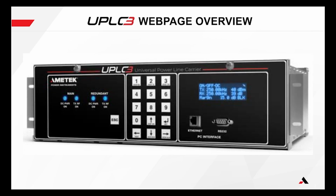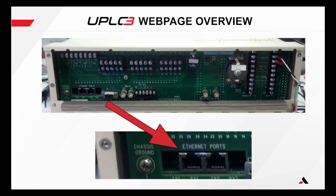The external connections to a UPLC3 are identical to earlier UPLC and UPLC-II. There is a front 9-pin RS-232 serial port and a front RJ45 Ethernet port for local programming, and rear RJ45 and/or fiber ports to connect to a network.